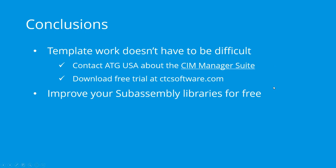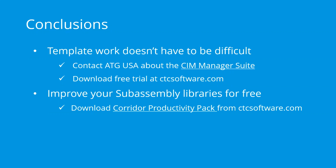Those of you who do a lot of transportation work, okay, corridor modeling, it's all about the source subassemblies you're using. And effective subassemblies make a big difference. Go and download that corridor productivity pack. Like I said, it's free. You can take and open those PKT files right in Subassembly Composer, tweak them, adjust them to your liking, make them your own, okay?